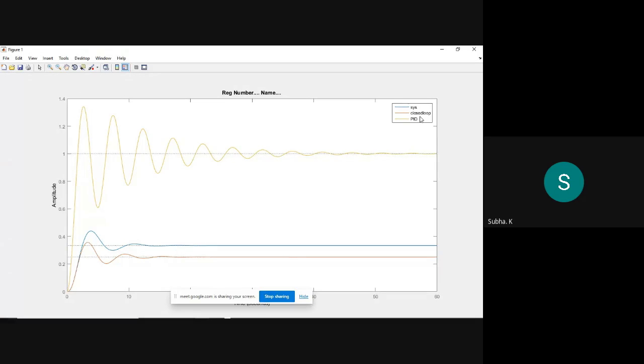Without the inclusion of the PID controller, without closed loop, it is the open loop system response from which you have calculated L and T. Okay, so at what value is it settling? Is it 1 at this point? No, ma'am. Again, the closed loop also, if you observe, is the response settling at 1? No, ma'am. Okay, that is why I got confused. So if you see after the inclusion of the PID controller into the system, where does it settle now? You can see.